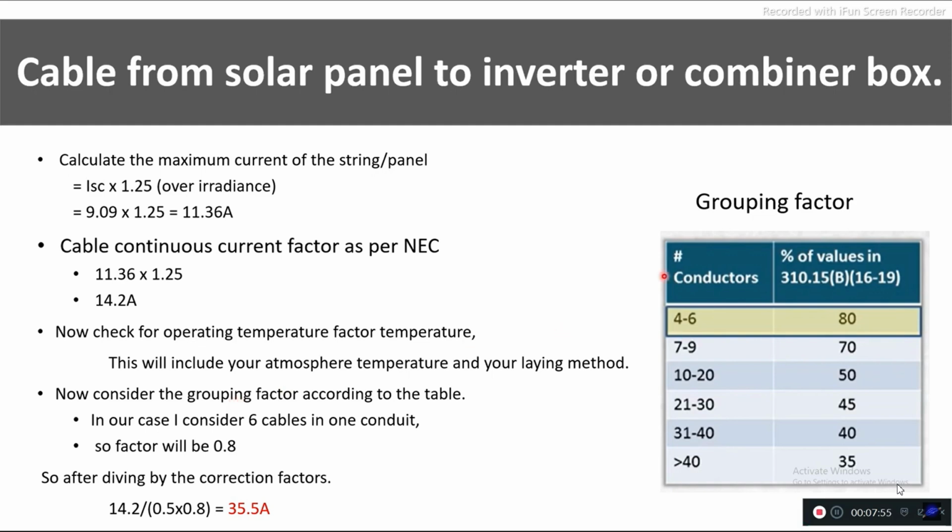So you can refer to this chart for your standard calculations. Not more than 40 cables are used or placed in a conduit. So this chart is very much sufficient for you guys. So here, as per our example, I'll consider 0.8.